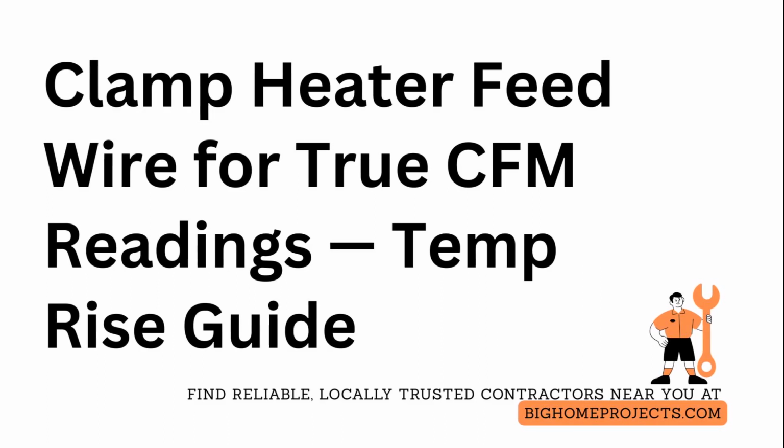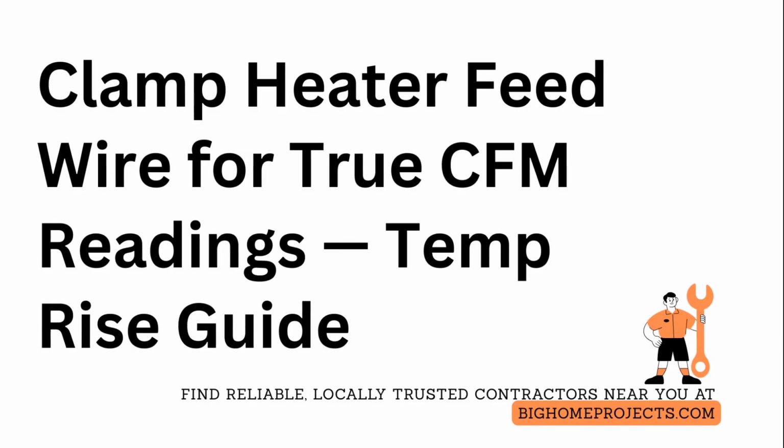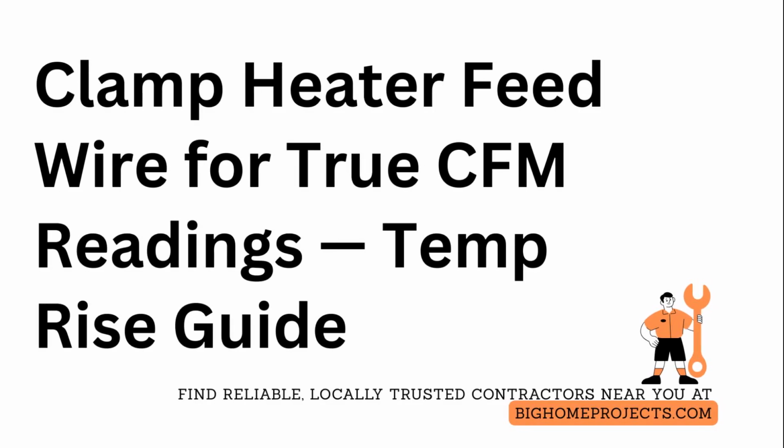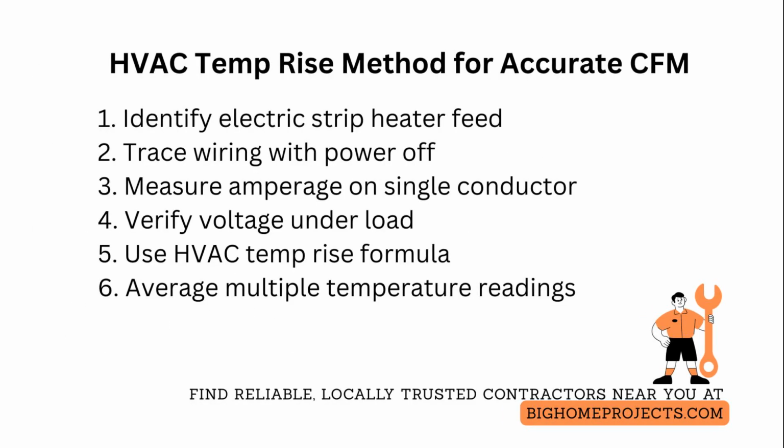HVAC temperature rise formula to measure airflow CFM. Use the heater wattage divided by the product of temperature rise and specific heat to get accurate cubic feet per minute numbers fast. For a reliable measurement, first identify the electric strip heat feed wire at the heater terminal.